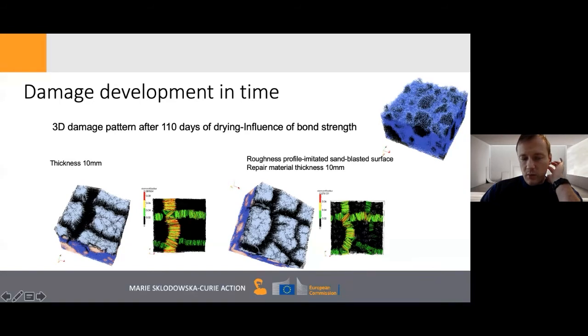So in this case, we applied, I think Erik has mentioned this, periodic boundary conditions. So we have periodic boundary conditions in two directions, if I look from the top, vertical and horizontal. So this crack continues here, and this crack continues here. So we can simulate cracks in this type of material, and by taking only a piece of material, using periodic boundary conditions, we are able to simulate a representative part of the material.